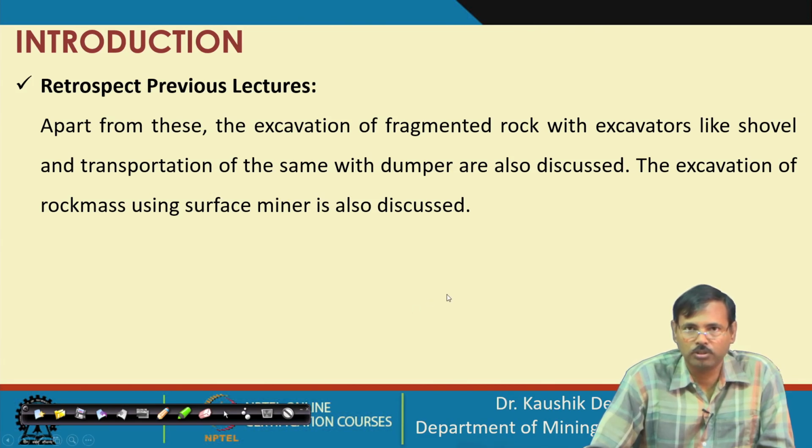We are now continuing with high wall mining. In the last class, we introduced high wall mining, which is a new technology. We have seen it is basically excavation from the high wall without entering into the drive. It is the construction of a drive inside the high wall without entering into that drive, and the drive is self supported with 2 web pillars kept on both sides.